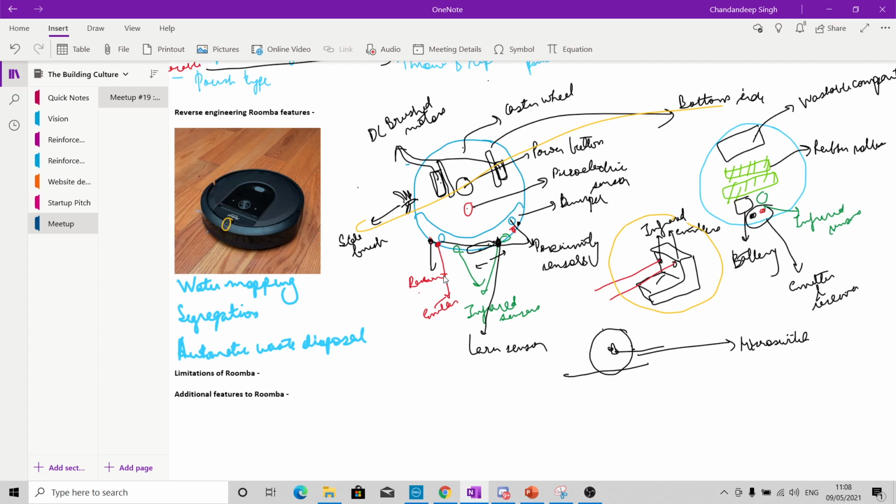It knows this object is at this distance from me. In SLAM, it can randomly move and still build the map, so there is no need for optimal path planning. But after the map is there, the optimal planning starts. The planning algorithm decides the optimal way of reaching from this point to that point, and for that you need to know the map. The map has to be known, then it starts making the optimal path.